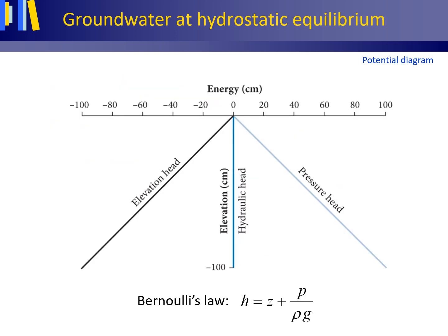And let's start off with groundwater first. Because we take the existing air pressure at the water table as a reference or zero level, the pressure head at a water table that can establish itself freely is defined as zero. When we apply this for groundwater under hydrostatic conditions, that is, no vertical water flow, and take the water table as a reference level, we can draw this figure.